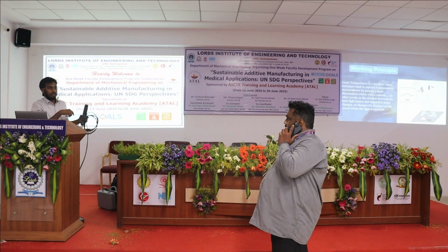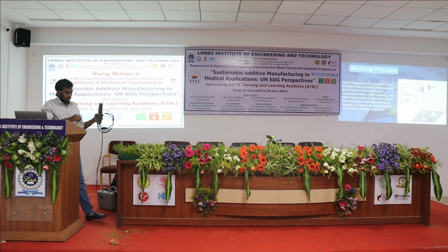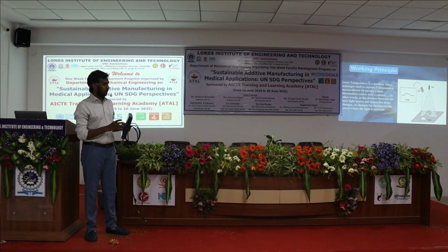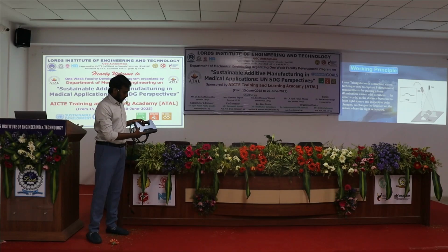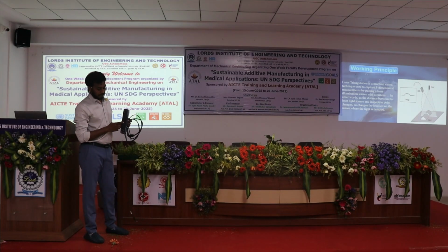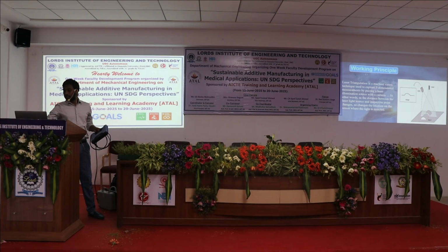So it is a white light scanner, where these LED lights produce some light like a kind of laser, but it's completely safe. It depends upon the component. Then it will be captured by the camera. Like here, you can see it displays on this product. The camera captures this deformation of the product in point cloud data.